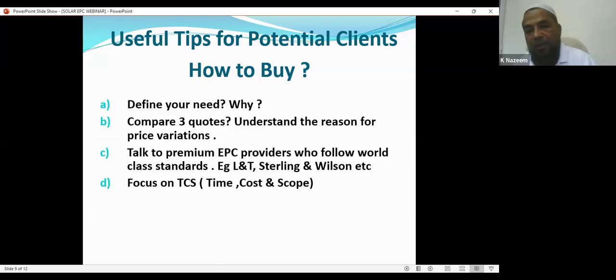The cost. In the beginning, the cost may be very less. For example, MMS is a component in a solar plant, and if it is not galvanized, there is a standard that 80 microns galvanization is necessary to prevent corrosion. If the galvanization is not done, then within 5 to 10 years, the structure will collapse. And then the cost will definitely be double the cost of the previous one, because you have to replace the complete structure.